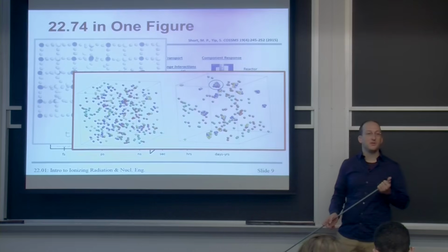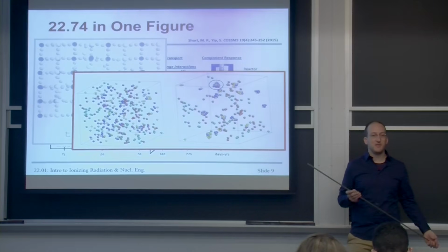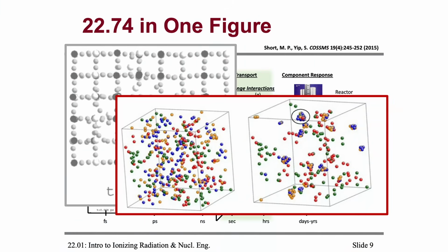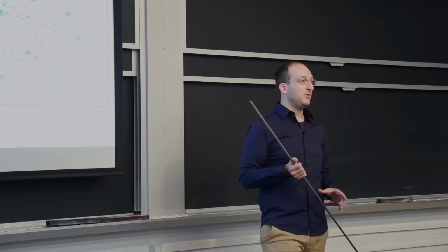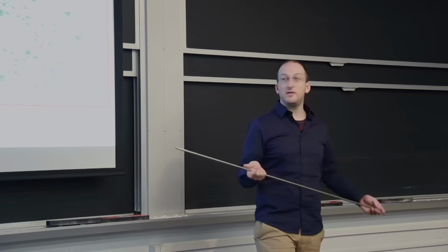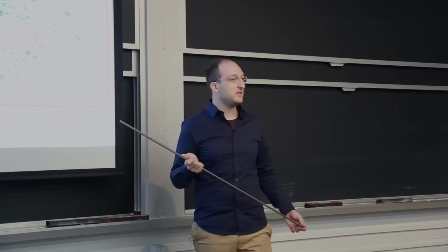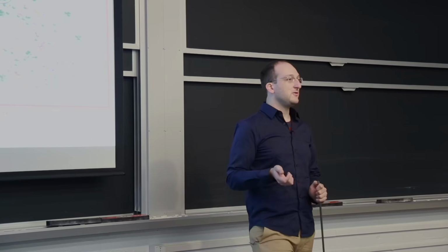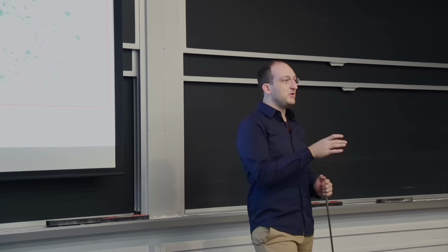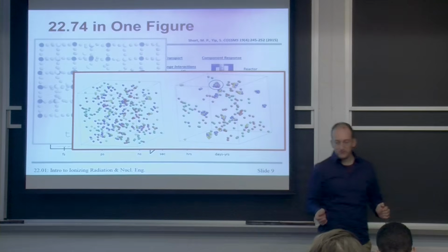They can diffuse. They can be transported ballistically by more radiation damage. They can move by all sorts of different mechanisms and eventually find each other, forming what's called clusters. So a bunch of those missing atoms could find each other and make a hole, which we call a void. A bunch of the extra atoms shoved in between the other ones can form things called interstitial clusters. We say interstitial because it's like in the space in between where you'd normally find some atoms.